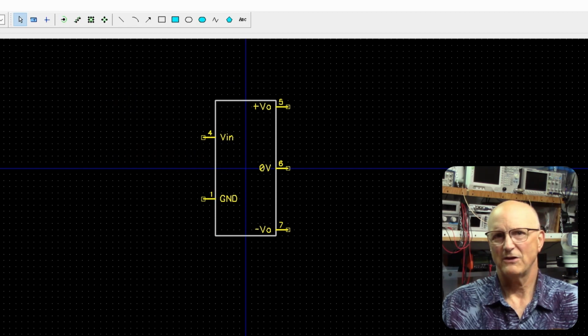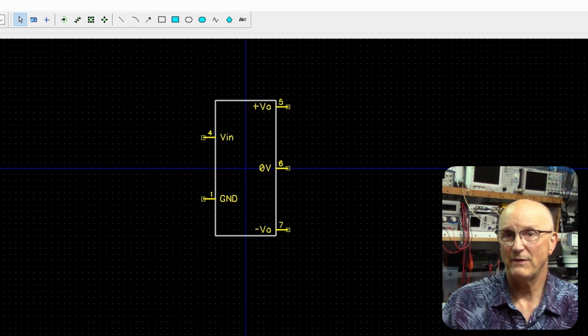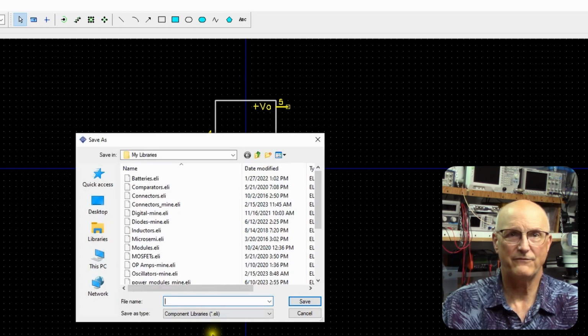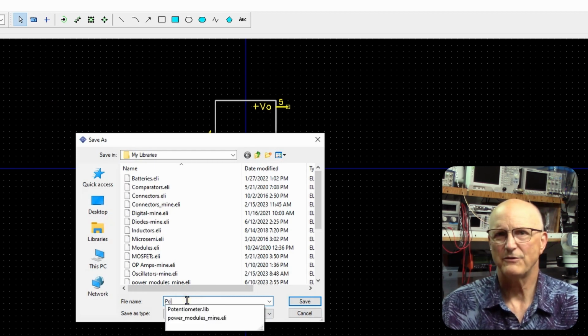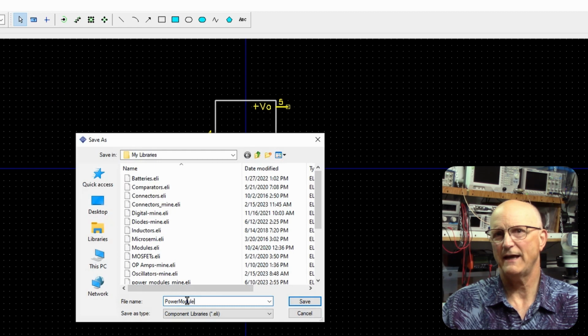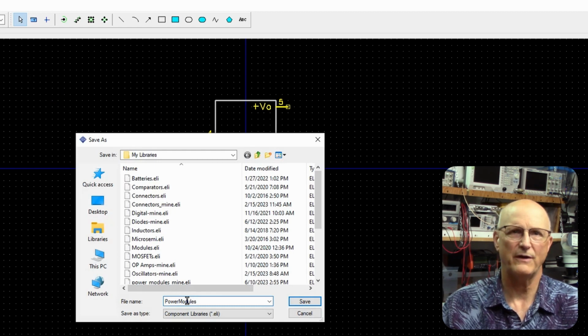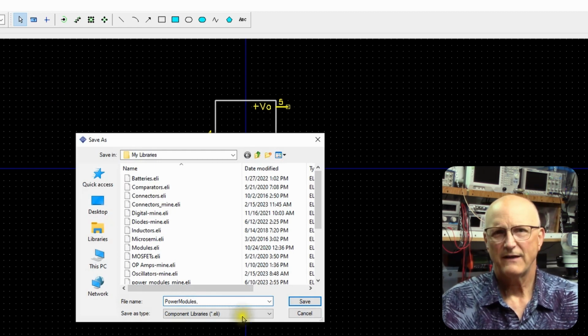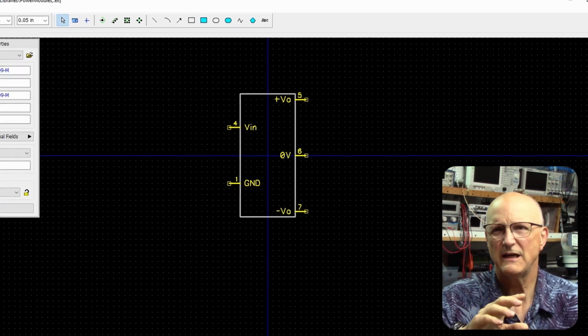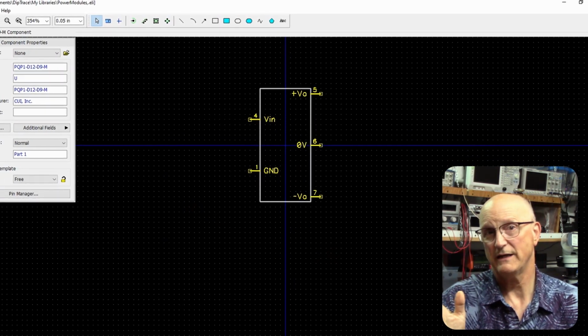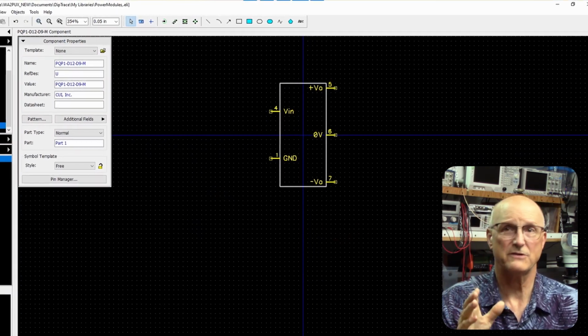Now we save the library by clicking on the Library menu option and then Save from the pop-up menu. We will revisit this once we get to the PCB side of things to add a PCB pattern or footprint. With that said, the only reason that I am postponing this step is to keep all of the PCB related stuff together in one series of videos.